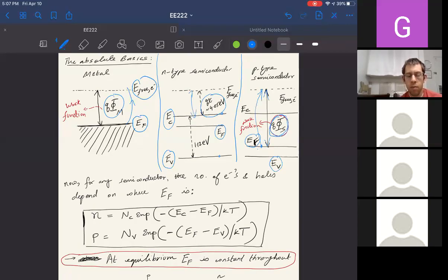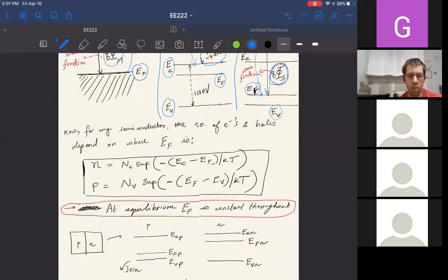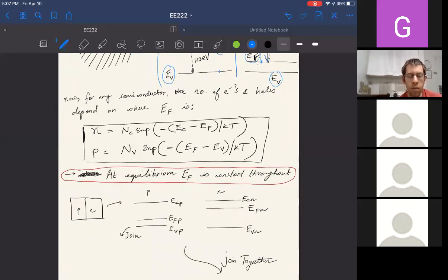These are important because when you choose different materials for your gate, your threshold voltage is going to depend on these different work functions as well as these other parameters. So you need to enter the correct material parameters to get the threshold voltages.